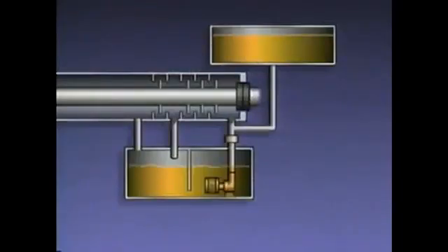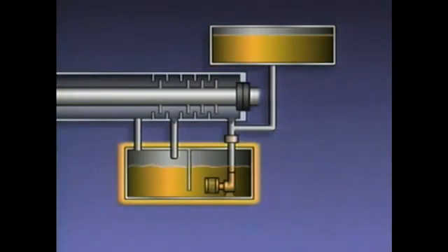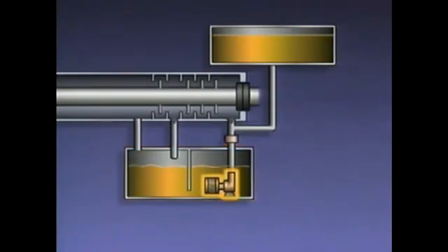Both mechanical seals and labyrinth seals may be used with a seal oil system. Some compressors rely on a seal oil system to prevent gas from leaking out of the compressor casing along the shaft. The simplified seal oil system illustrated here includes a mechanical seal located around the shaft at the point where the shaft penetrates the compressor casing, and a labyrinth seal. The seal oil system also has a seal oil reservoir, which is divided into 2 compartments. The reservoir contains a strainer and an oil pump. The system also has a head tank and a check valve.